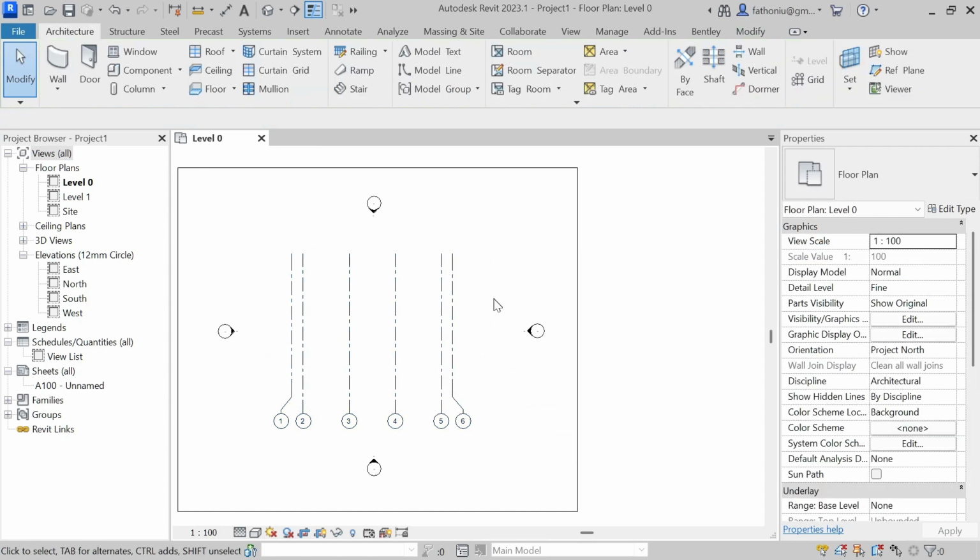Okay, you can select from right to left like this. Any object that intersects with your rectangular selection box will be selected like that. To release the selection, you press Escape or click any location.